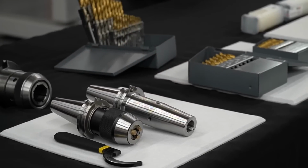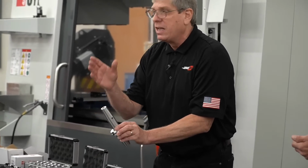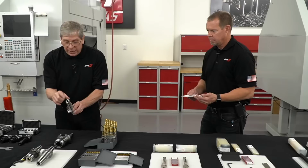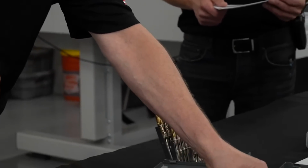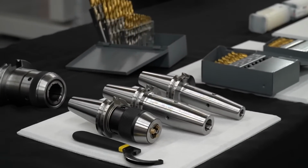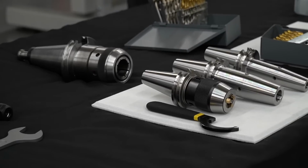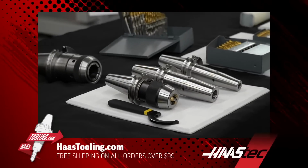I love these holders because they've got the holes right in the face for the through spindle coolant, so you don't need slots down your end mill, or some have a hole through the center of the end mill. You can put any end mill in there and have TSC coolant spraying right at the tip of the tool, down the flute. So there's a couple of sizes of shrink fit, and here's a drill chuck, which comes with the key. Fantastic offering of new tool holders that'll be coming soon. Now, we've gotten a lot of requests for these, and these will finally be coming soon.